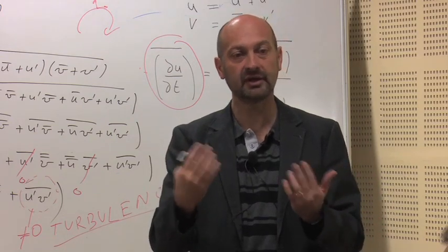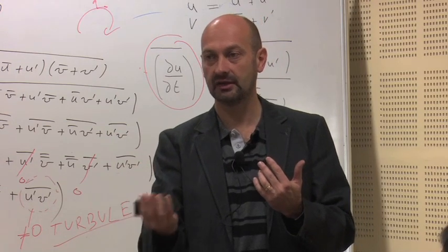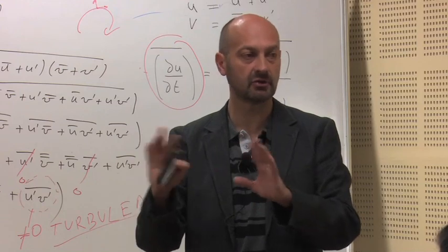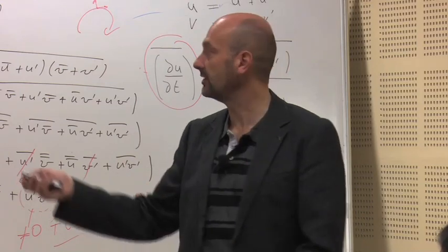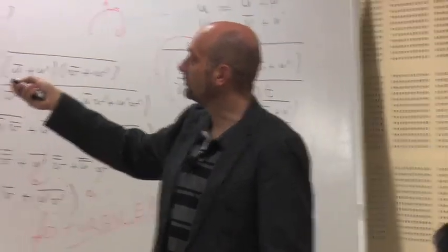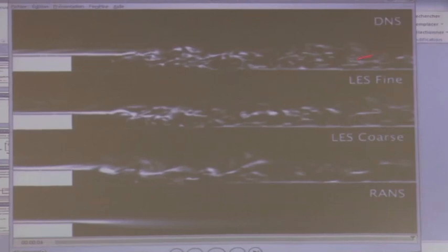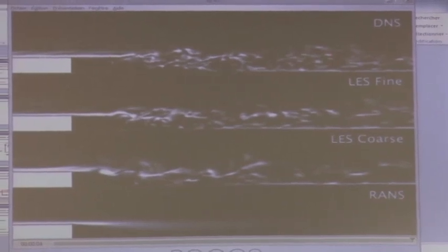You have to understand what are the errors coming from your choices in the CFD modeling, the CFD boundary conditions. Many problems are coming from the boundary condition. For example, here you have a boundary condition because you have to stop your domain at some point. But in reality, this flow is continuing in an experiment.